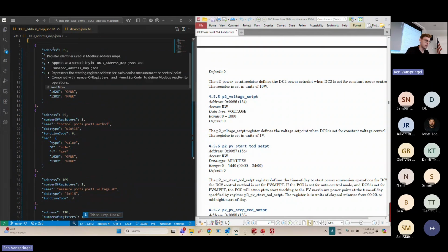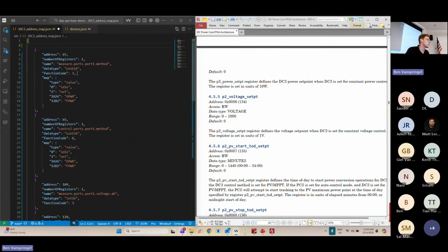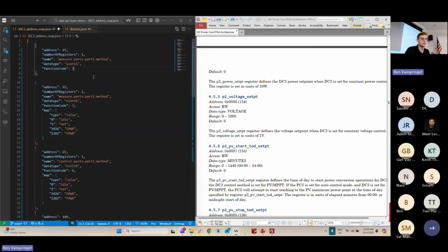There is one more thing that I want to show you here as well. Another register that is really, I wouldn't say important, but it's really useful because probably some of you know that with Modbus, you can read multiple registers at once, so it's more efficient than having to poll all these single measure registers individually. That's time consuming. Your Modbus server and your client will get overloaded.